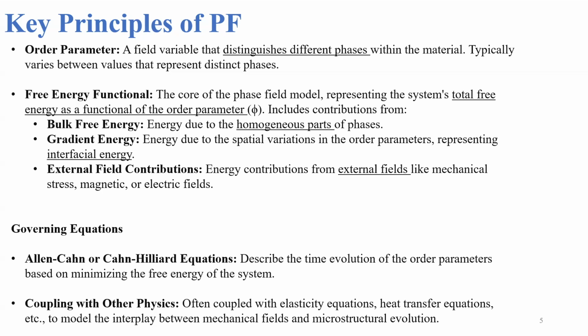Some of the common governing equations are the Allen-Cahn and Cahn-Hilliard equations. They describe the time evolution of the order parameter based on minimization of the free energy. So I would note this term, minimization of free energy, carefully. This is the case for most physical modeling processes anyway. And of course, it can also couple with other equations in physics, such as the elasticity equation, heat transfer equation, and so on. That can help us model the interplay between the mechanical field and the microstructure evolution.